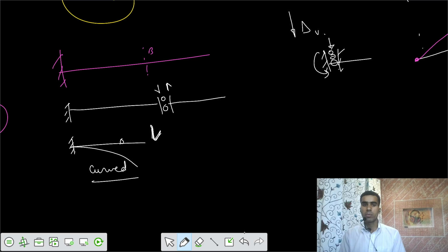That means this shear would be 0, because this is not possible. If this is not possible, that means the entire shear of 1 unit has been transferred to the other side. For this side there is no support from this side. You are applying a shear of 1 unit upwards, so once you apply the shear of 1 unit, the entire section moves upwards by the same amount.